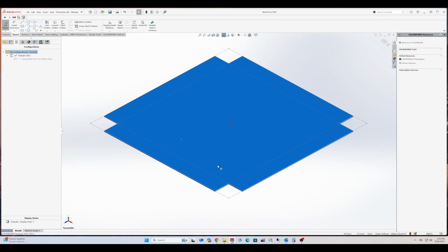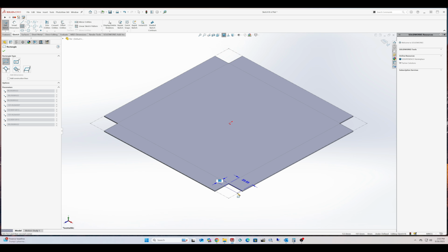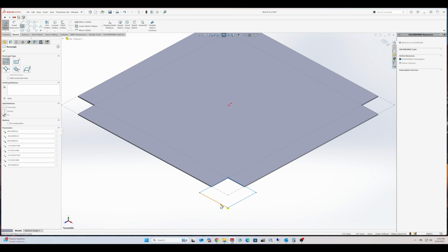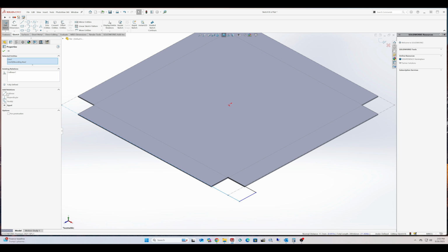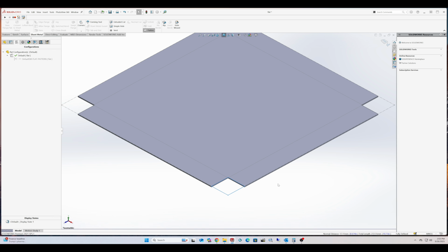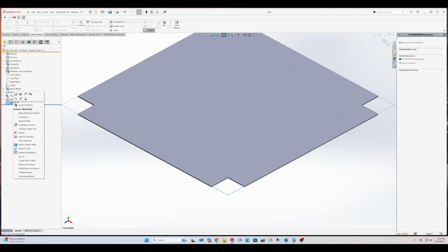But in order for my flat pattern to be correct so that I can form this in the machine properly, I'm basically going to have to square up those corners and then put a chamfer on it, whatever I'm going to need that chamfer to be to get in the machine. In this case, it's going to be around 18. So as I draw this in, I'm drawing it just like you would draw any other time when you're using 3D tools. I'm just going to sketch in that corner real quick, and then I'm going to do an extrusion on that.